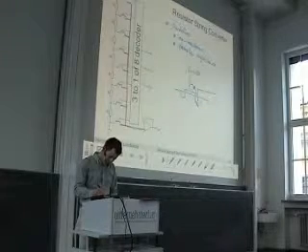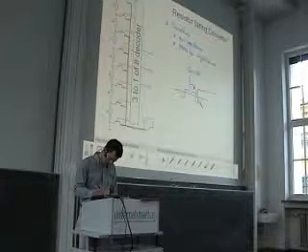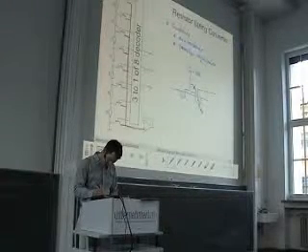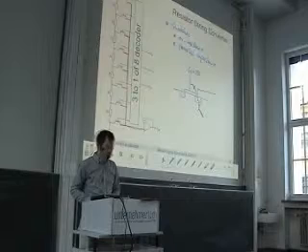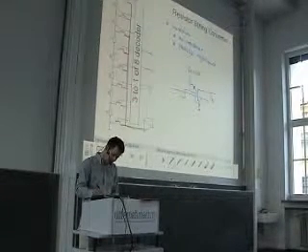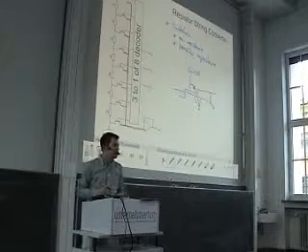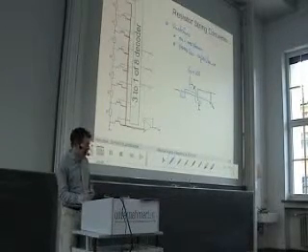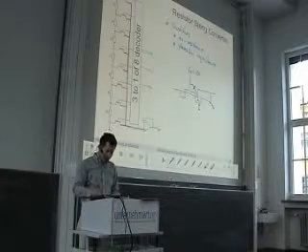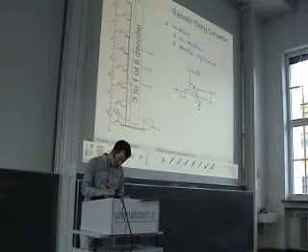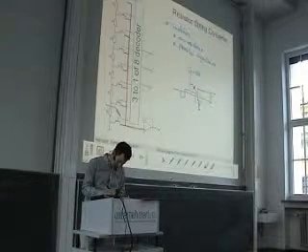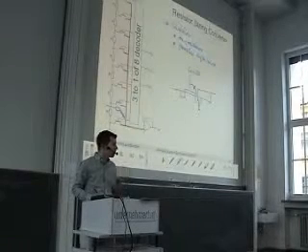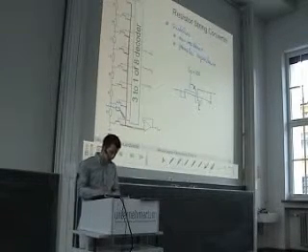We have a parasitic diode from this node to the bulk, which also causes parasitic capacitance. And of course we have wiring capacitance here. So we can simply say each transistor contributes a certain amount of capacitance. And this means that if we look at this path, for instance, we have our on resistance of the transistor. So one transistor is turned on, for instance this one.